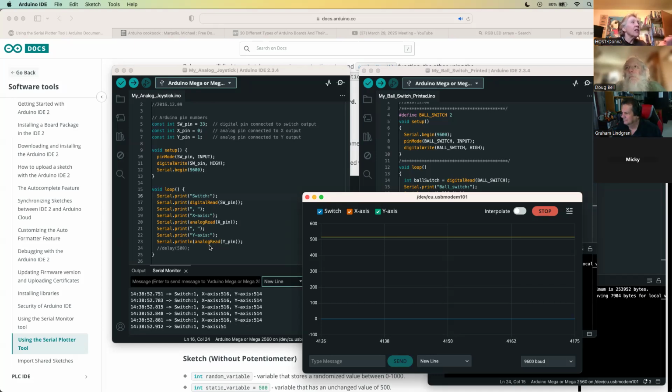Say, for instance, I know for sure with GPS boards, etc., that you can interface directly with the Arduino, and then a lot of other boards and parts have a specific default baud rate, but they also specify what the other values can be, what are supported by that part. So that's a very important characteristic to be looking at.